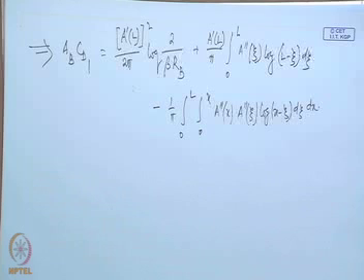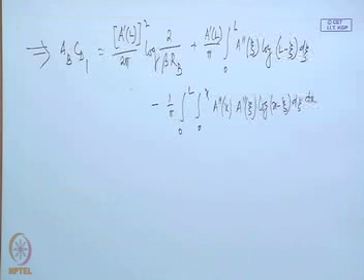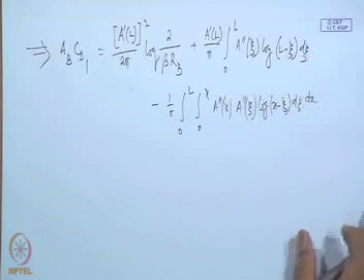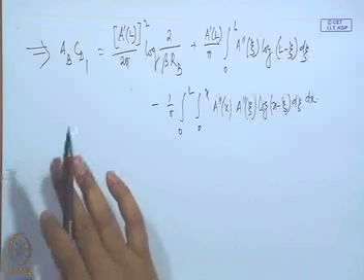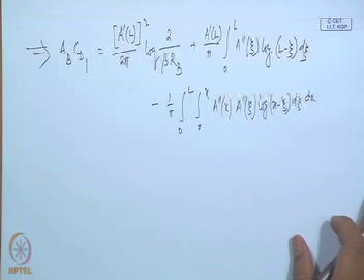So, this is the expression for the drag that comes in axisymmetric flow over a slender body with pointed nose in supersonic flow, due to the pressure distribution on the surface of the body, that is excluding the base pressure drag.